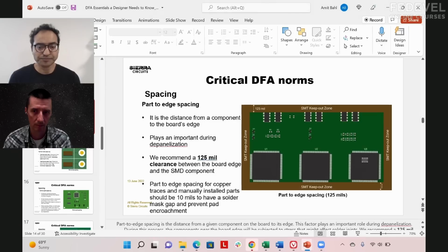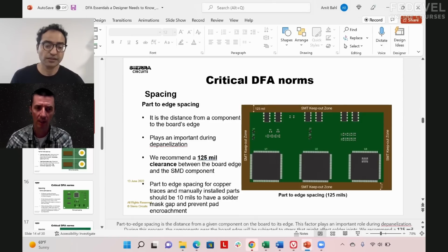That's one thing. The second thing is when boards get really tiny, don't use a mechanical router bit to depanelize. Don't snap and file. I would say start using laser depanelization. Can you do that? I didn't know you can do this, because this is exactly something my friend had many problems with.